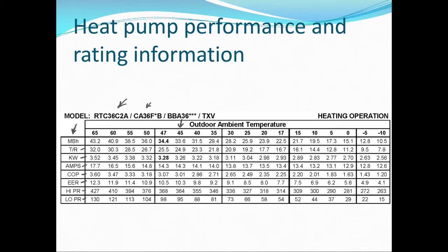Very, very helpful. Couple other things that I want to point out on this chart. You'll notice if I go down to 10 degrees, 0 degrees, if you look at the coefficient of performance, you're going to notice that the COP, even at 10 degrees, is still 2.0, or 1.63 at 0 degrees. So you're still pretty efficient, but the dilemma that you run into is that you're not going to get enough capacity of heat out of it.